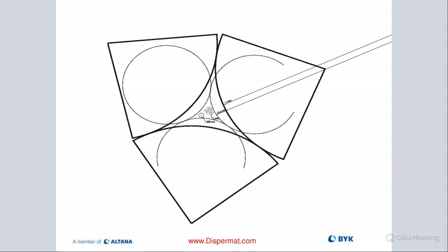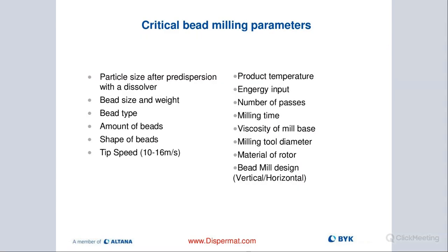As the beads collide together, and this is all in a suspended state in liquid, there is all this shear force being created, and that's causing these particles to break up. So it's not that we are crushing the pigment in the middle between the beads. Remember the rubber duck, it tries to get away, and that's what's causing the breakup of these van der Waals forces. So that's really what's going on inside of our mill. We're doing the process of milling.